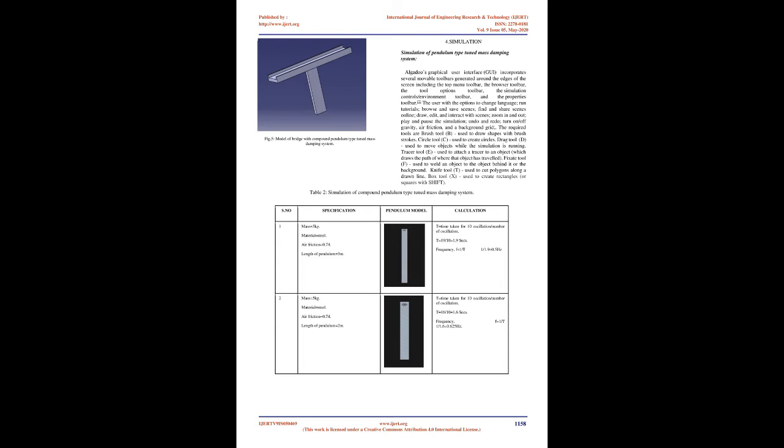A simple pendulum-type tuned mass is used with bearings, which can be eliminated by supporting the mass with cables which allow the system to behave as a simple pendulum attached to a floor. Movement of the floor excites the pendulum. The relative motion of the pendulum produces a horizontal force that opposes the floor motion. The rigid link moves in phase with the damper and has the same displacement amplitude.